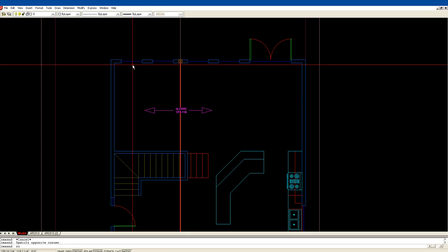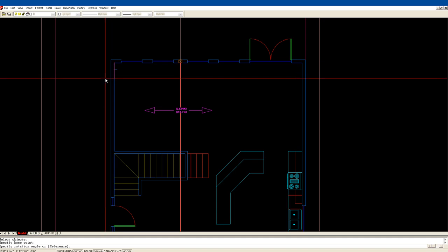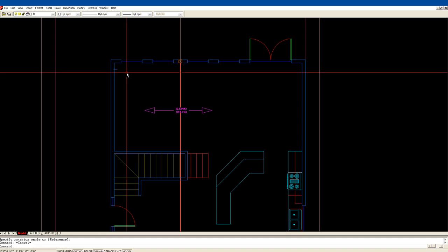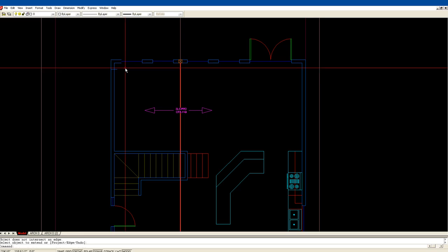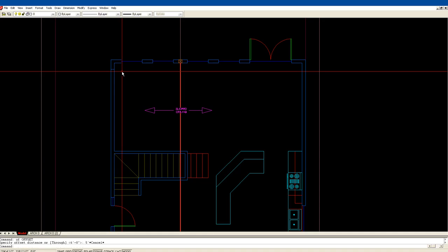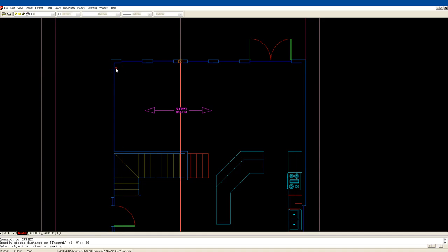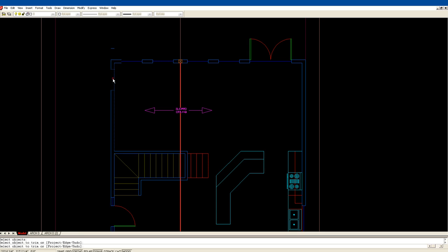But I'm going to rotate that one there, bring it around to there, so it's the same distance. Whoops, extend. There, trim, and I'm going to offset 5 feet. Actually, let's just do 3 feet. Offset 36. I'm thinking that's what he's going to change it to. Keep going in the wrong direction. I'm clicking, clicking, clicking. Okay.